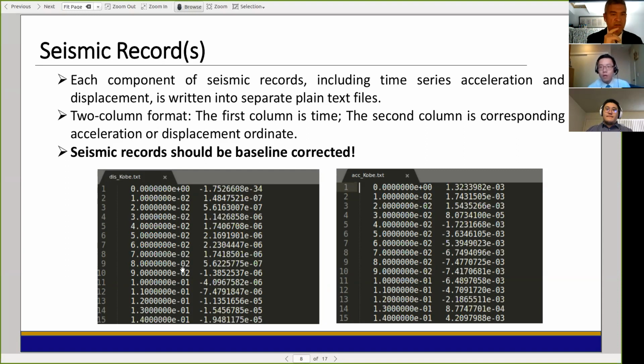It's important to have properly done, corresponding displacement and acceleration waves that are propagating, in this case, as one-component waves, P waves or SH or SV waves, but they have to be properly baseline corrected, and they have to be proper physics-based waves. If the wave is not physics-based, then you get all sorts of high frequencies that are not physical, essentially. Yes, that's true.